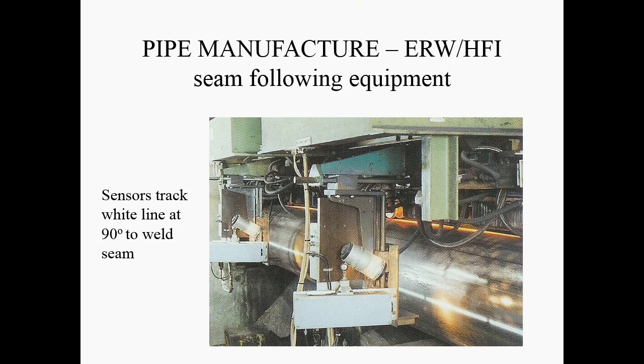Obviously, if you're going to have a welding station and you've got those squeeze rollers, you want the weld seam to be right between the squeeze rollers, not to run under one squeeze roller then under the other one and move around. So there's a whole sort of motion there. And those rollers can be adjusted and the pipe can be twisted to make sure that that happens correctly within a small range. It's not something that you can take a 90-degree change.